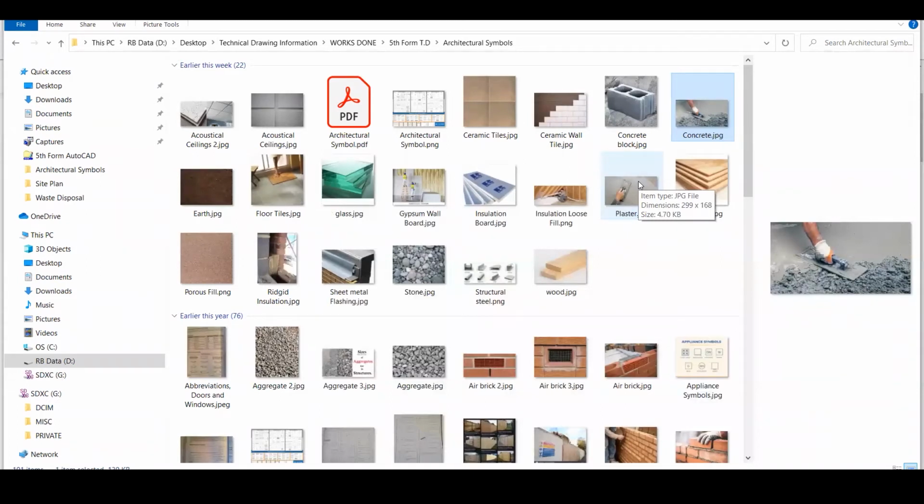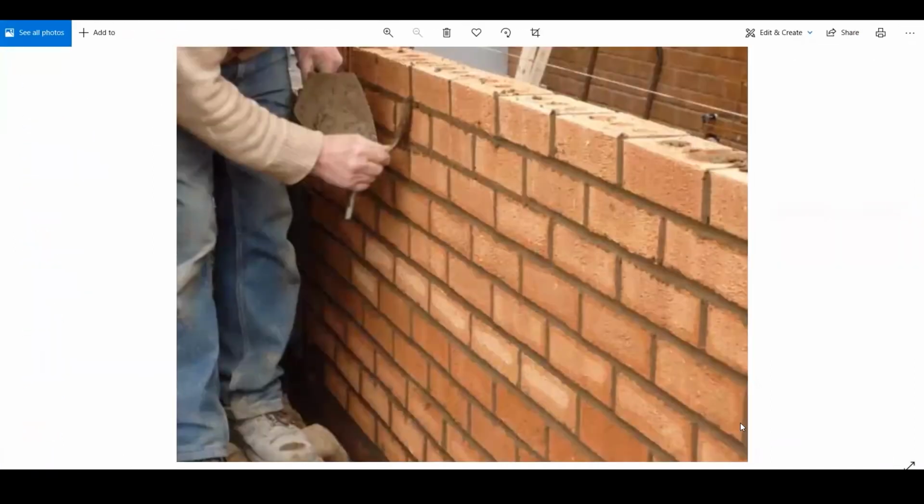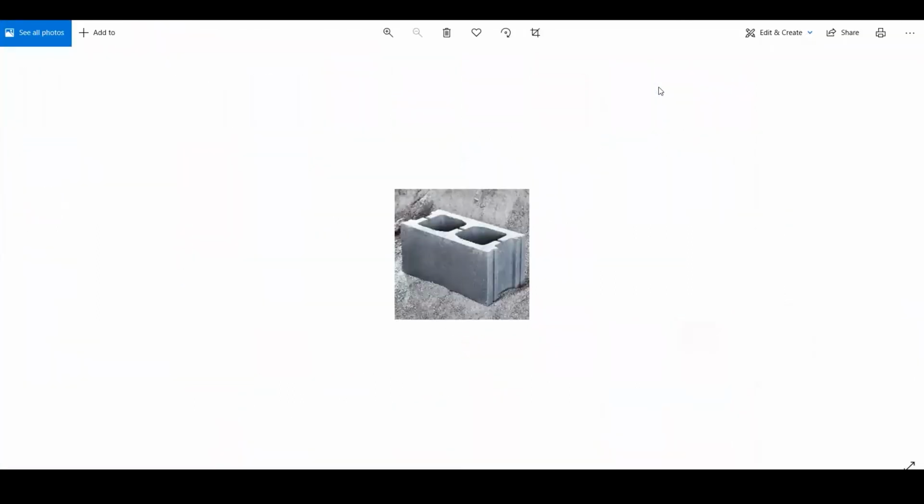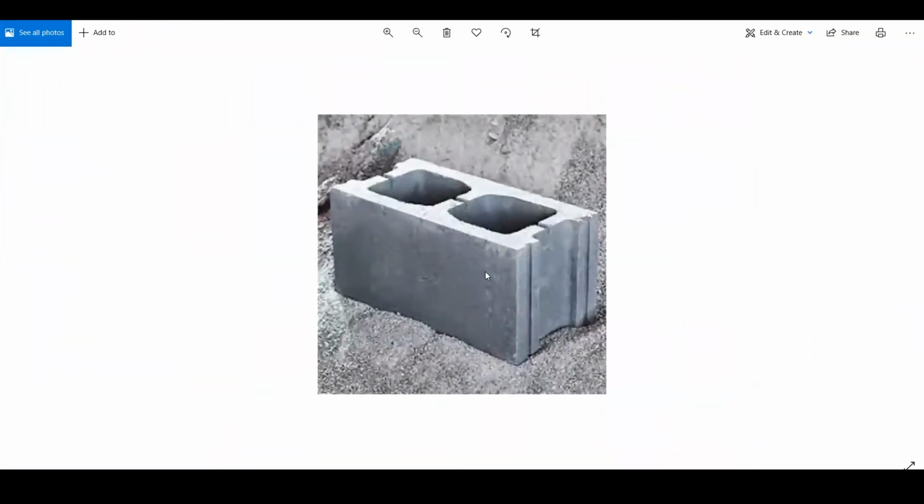So first you set up your bricks, then you don't want to see, right, some people don't like seeing these lines here, the brick bonding pattern. Well, this is fairly beautiful when you're using red bricks. But if you're using these concrete bricks, when you place them and you set them up and you have them bonded, the pattern there isn't that beautiful. It can look quite untidy, and the finish can look tacky if you leave it as a finish. So what happens is people apply the plaster to hide these lines. So it just seems as one big mass of material, one big fill of that material.